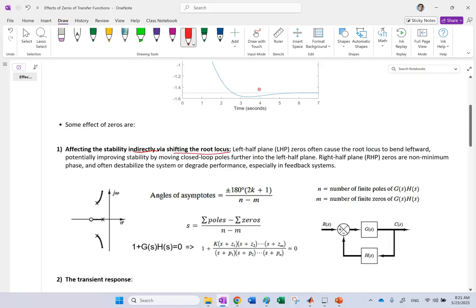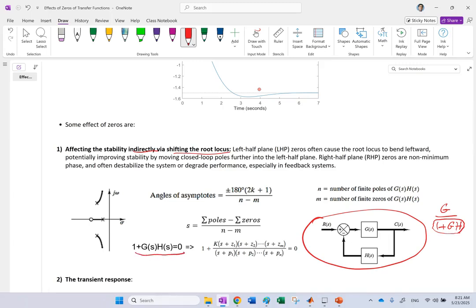So what is root locus? I have a couple of videos in this controls playlist where I showed you how to create root locus and also how to design a compensator based on root locus. But basically, root locus is the location of the closed loop poles if you have some gain in the system that you can change. For instance, if you consider this control system, you know that the closed loop transfer function is g over 1 plus gh, and so the poles of the system are the roots of this characteristic polynomial, so we have to set it equal to 0.